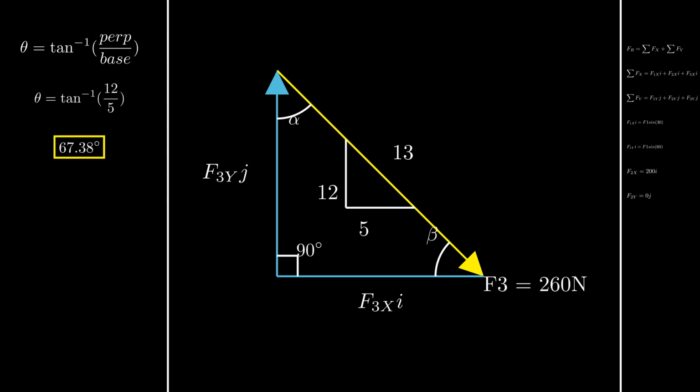But how do we know whether the angle that came out after conversion is angle alpha or angle beta? Whenever we convert a slope into an angle, the angle is always measured from its base. That's why the angle that came out after conversion is angle beta. And we can find angle alpha by the sum of angles formula, and the magnitudes of its components by the sine law.